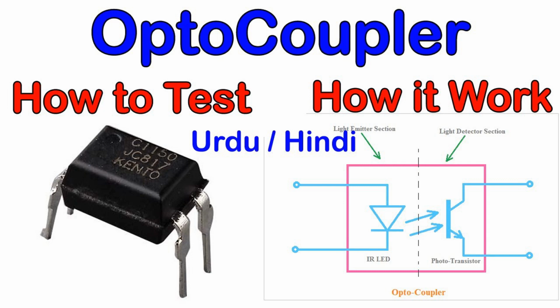Attenuation. In some cases, a signal may be too strong or have excessive voltage levels for the subsequent components or systems. Signal conditioning can include attenuation, where the signal's amplitude is reduced to an appropriate level using voltage dividers or attenuators. Filtering. Filtering is essential for removing unwanted noise, interference, or high-frequency components from a signal.